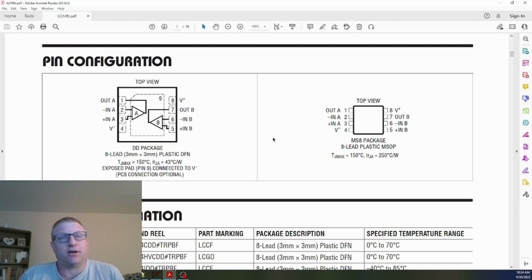Some op amps also have a resistor. It is the input bias offset resistor. And so it'll have two pins, and you can put a resistor on there to try to balance out that input bias current to make your voltage offset 0. Instead of, like in this one, it was 100 microvolts. Right, so they actually have some op amps come with those offset pins to allow you to put a resistor to offset the offset voltage and make that voltage offset equal to 0 with that resistor.